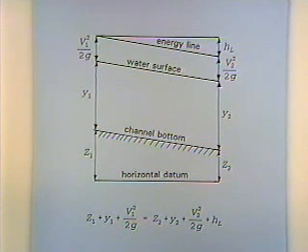And HEC2 is a program that does standard step method, a solution of the energy equation, water surface profile computations. And HEC1, the hydrology, gets you the discharge rates associated with given probabilities, and then the water surface profile computations delineate how high the water's going to get and what land's being covered.